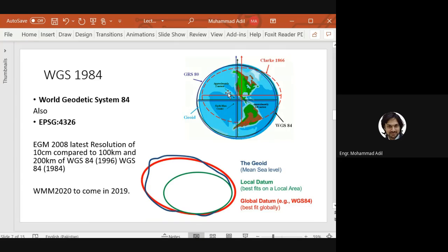So this equation is the surface of the ellipsoid, and somewhere it gives points which are outside planet Earth, and sometimes it gives us points which are inside the planet Earth, not on the surface. So Clark 1866 method of locating a point using XYZ system was very faulty.